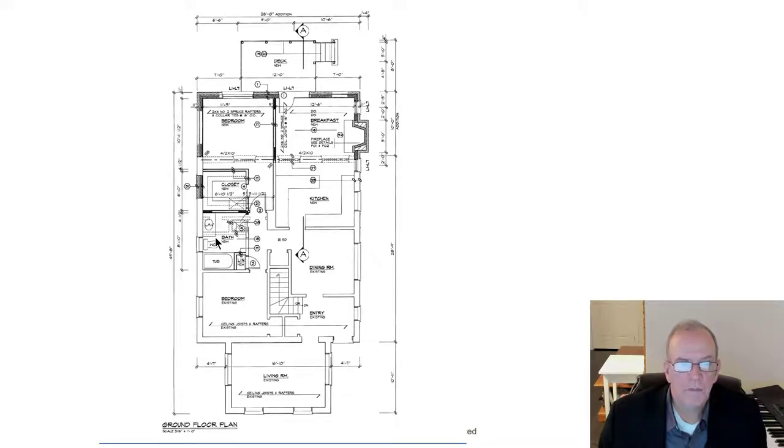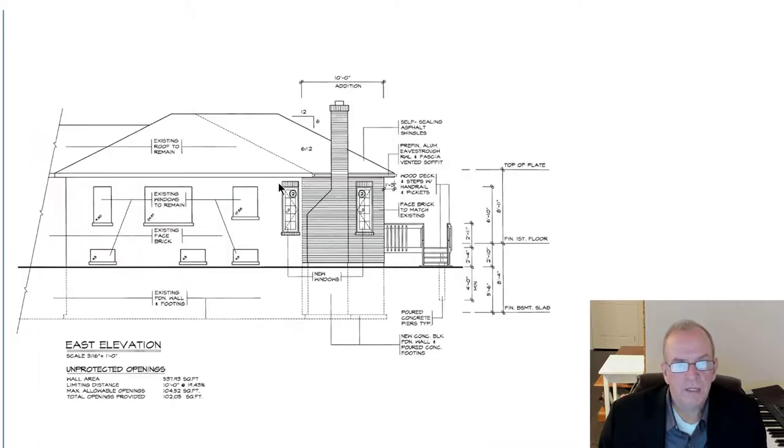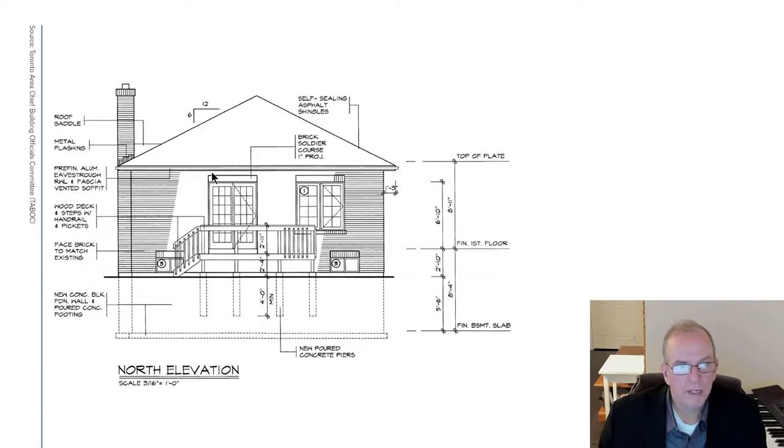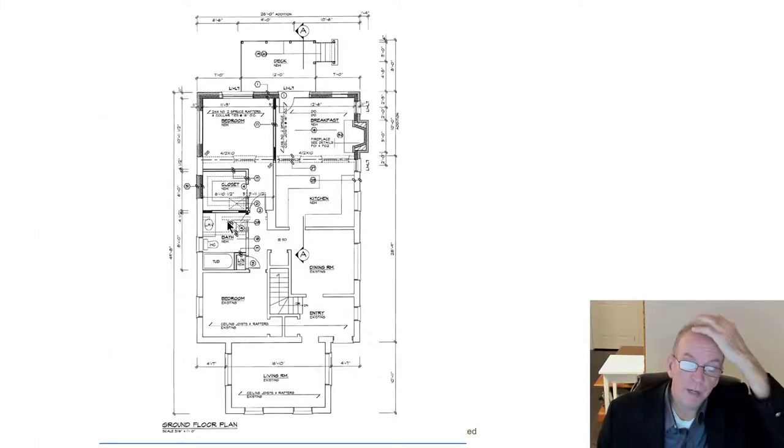So you'd have to make sure that you're looking at what direction the ceiling joists are in this back section. Here it shows the ceiling joists and rafters are running this direction. I'd want to know, is that the case for the whole house? Probably it is. If I take a look at the existing house, it's a hip roof, so I really want to investigate that to make sure. I wouldn't want to make a judgment call that they're running the same way all the way through a house. Likely they are, but with renovations, you have to do a thorough renovation inspection to be sure.